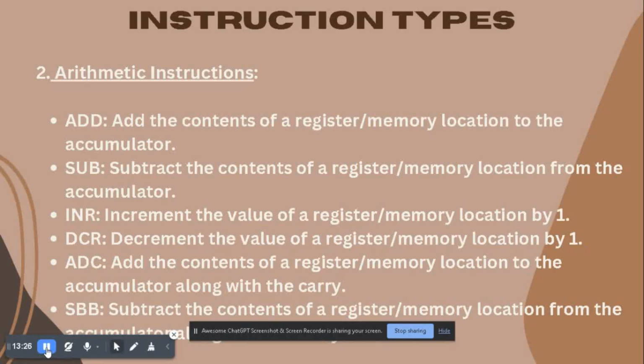ADC. The ADC command is used when we want to add the content of a register or memory location to the accumulator along with the carry. We use the ADC command because sometimes when we perform an addition, there are cases where a carry must be generated. So we use the ADC command to add the carry in the further addition.